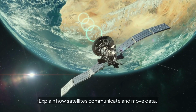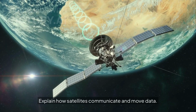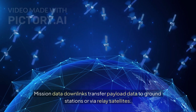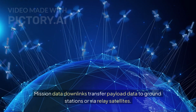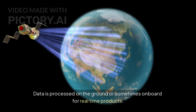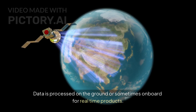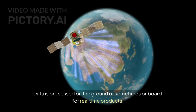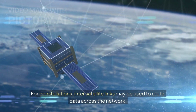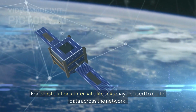Explain how satellites communicate and move data. Telemetry, tracking and command, TT&C. Mission data downlinks transfer payload data to ground stations or via relay satellites. Data is processed on the ground or sometimes on board for real-time products. For constellations, inter-satellite links may be used to route data across the network.